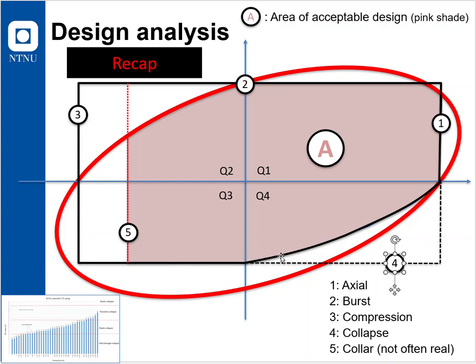And then this line is the middle thing. It should be 2 of them theoretically. One going here, slightly lower for the transition collapse, and then one parallel a little bit lower for the plastic collapse, and the strongest, the yield, should follow the von Mises.